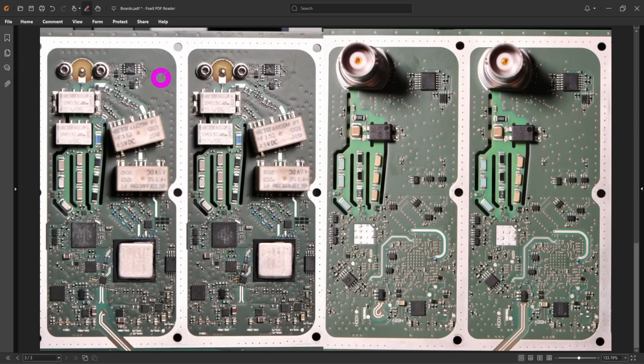Now the front end of this oscilloscope, much like every oscilloscope, has to convert a single-ended user input into some kind of a differential signal at the nominal input level of the ADC, almost always a fixed value. And that's not an easy thing to do on its own, and not every front end is the same. For example, in this particular oscilloscope, we do support some pretty impressive specs. First of all, we can support 400 volt peak at the input. That itself is tricky. You need to have careful protection circuitry for that. And then you can go all the way down to 500 microvolt per division, so you have to have pretty low noise, and you can do that at the highest bandwidth of the oscilloscope.